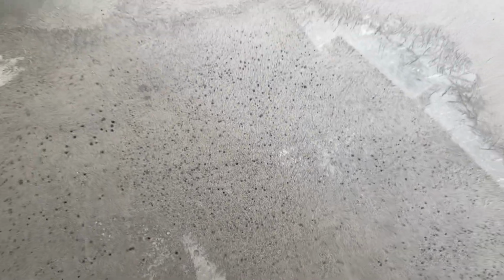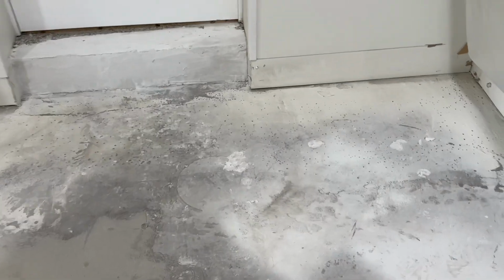Surface coatings, such as epoxies, urethanes, and other concrete overlays, act as barriers against water and chemicals. When applied to a concrete surface experiencing outgassing, the trapped air causes defects or pinholes in the coating. Coating defects can render the coating non-functional for its intended use.